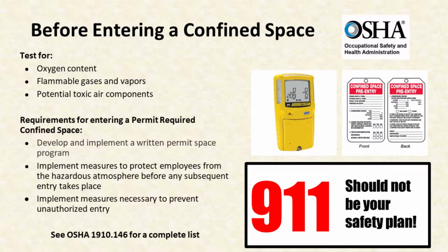The elements previously mentioned to test for before entering the space should also be tested for periodically while working in the space. During the time an individual is in the confined space, he or she should always have contact with the attendant. This will allow for easy communication, especially in the case of an emergency. All of the information previously mentioned, along with other important additional information, can be found in OSHA 29 CFR 1910.146.